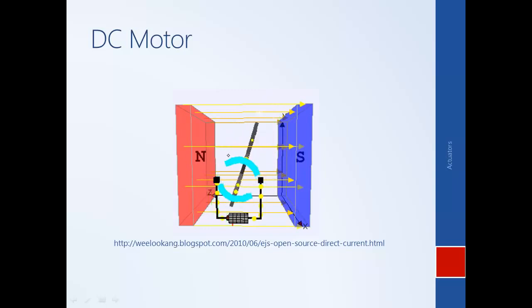So as it spins around, there's a break in the commutation, and it stops the current from flowing, and then when it reconnects, the current is flowing in the opposite direction. When there's this break, there's no current flowing through the rotor, and so there's no force being generated. But the rotor continues to rotate because of the momentum, the inertia of the rotor. And so it'll continue to rotate in the direction it was going until the commutator reconnects on the other side.